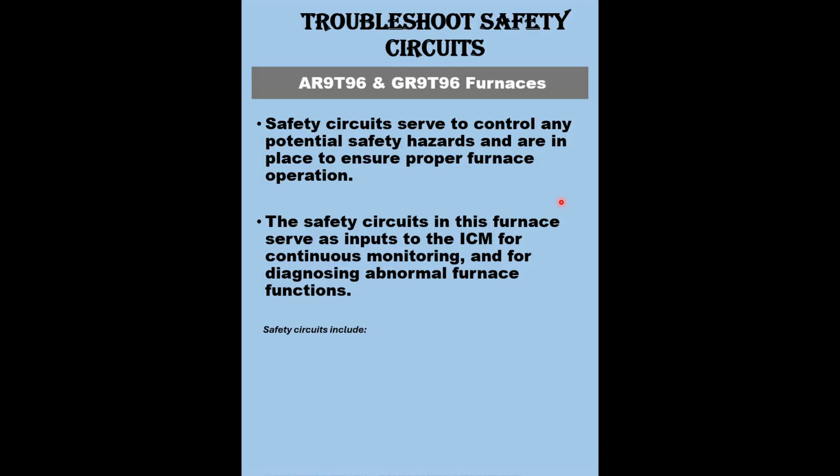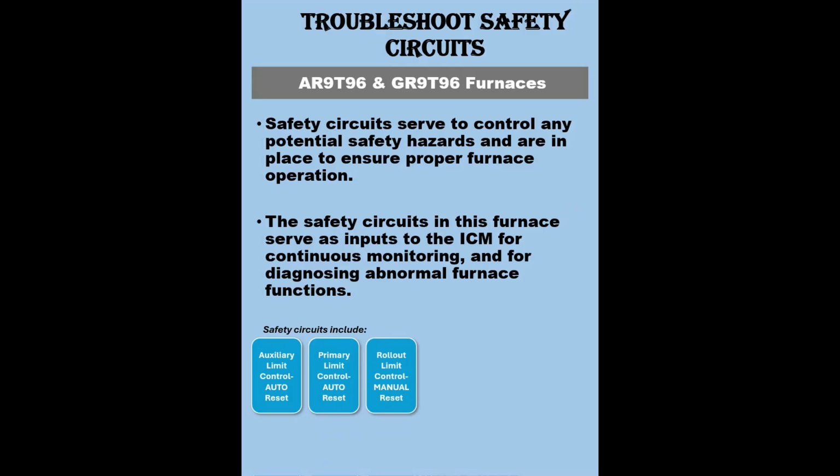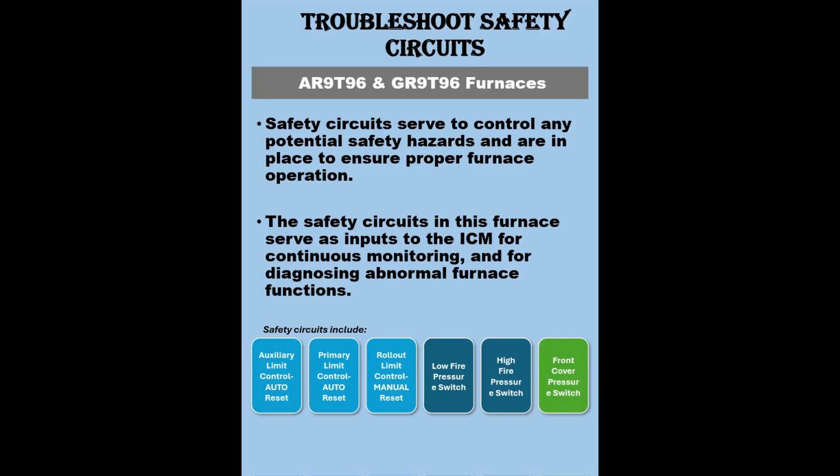Safety circuits include auxiliary limit control, which is an auto reset, primary limit control, which is an auto reset, rollout limit control, manual reset, low fire pressure switch, high fire pressure switch, and front cover pressure switch.